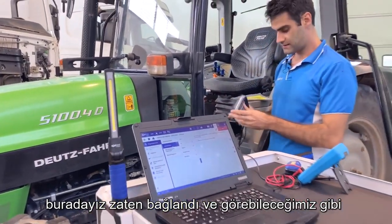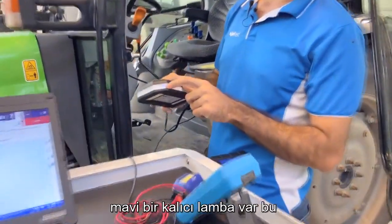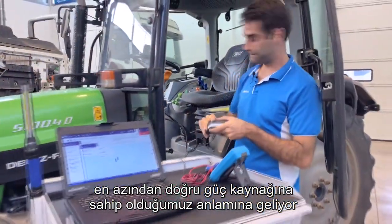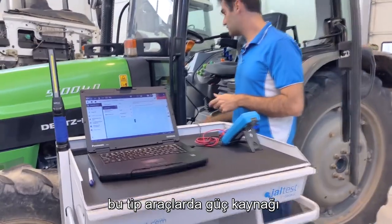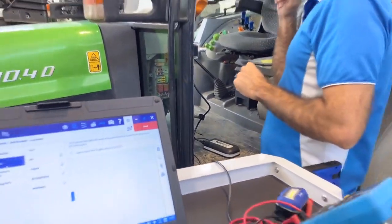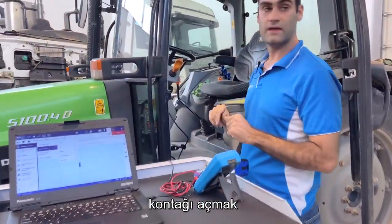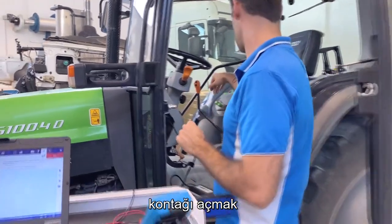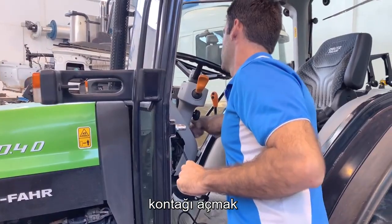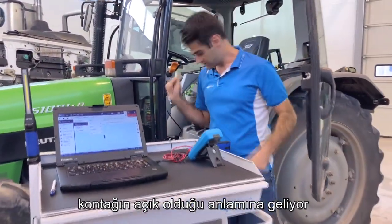It's already connected, and as we can see, there is a blue permanent lamp, which means that at least we have correct power supply. Power supply in this type of vehicles normally is 12 volts. And the next step is to give ignition on. There we are. That means ignition is on.